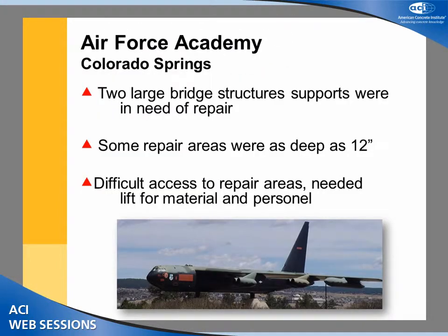This is another project called Air Force Academy in Colorado Springs. It's a U.S. Army Corps of Engineers project, actually. They had 2 large bridge structure supports that were in need of repair. Some repair areas were, again, as deep as 12 inches. There was difficult access to the repair areas, and a lift was needed for material and personnel. A ready-mix option was considered, but it was not practical for the repair areas, so they elected to go with, again, the repair material, which was an SCC, getting all the benefits and qualities of an SCC, but in a bag situation.